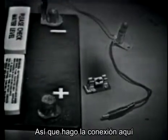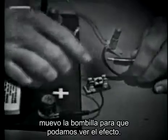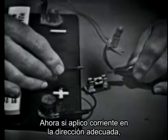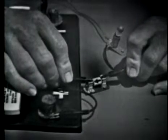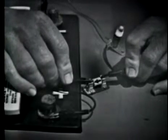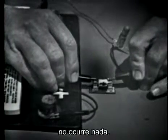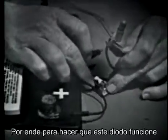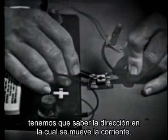Now, I'll make a connection here. Move the bulb in so we can see all of the action. Now, if I apply current to the device in the proper direction, like this, the bulb lights. If I turn the diode around and try to make current flow in the wrong direction, nothing happens. So to make this diode work, we would have to know the direction of current flow.